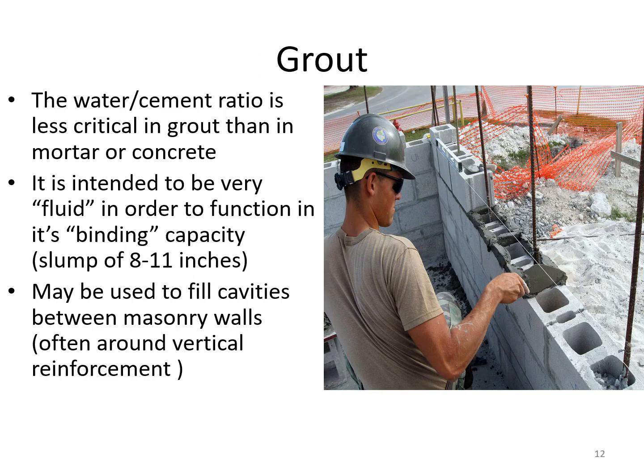So, grout. Now, what is grout? Grout, the water-cement ratio is less critical than in mortar or concrete. And it is intended to be very fluid in order to function in its binding capacity. You have a slump. You know the slump test, same as a kid at the beach taking a little sand bucket and turning it upside down. If all the sand sticks together and the outline of the bucket is there, there's no slump. But if you were to do it with mud, depending on the consistency of the mud, it would slump, which means it would start to expand out to the sides.